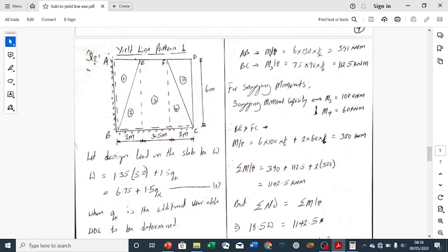This is because in this question, this side AD is unsupported. It does not have a support. So when you are assuming yield line, you do not assume that any portion will rotate about that axis. So in this yield line pattern, this plate A is rotating about side AB. This other big trapezoidal plate is rotating about BC, while this plate 5 is rotating about CD. There is nothing rotating about AD because AD is unsupported. There is no rotation at that point.